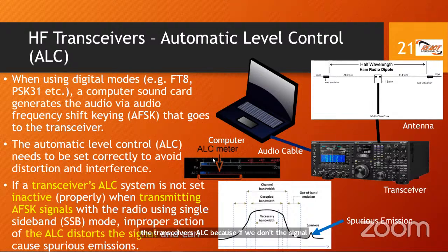So we're showing here on your screen what the ALC will look like. There's a range that it will operate if it's on. And this is an exam question. If a transceiver's ALC system is not set inactive, meaning properly, when transmitting AFSK (audio frequency shift keying) signals with the radio using single sideband or SSB, improper action of the ALC distorts the signal and can cause spurious emissions. Of course, this is a point of the exam.